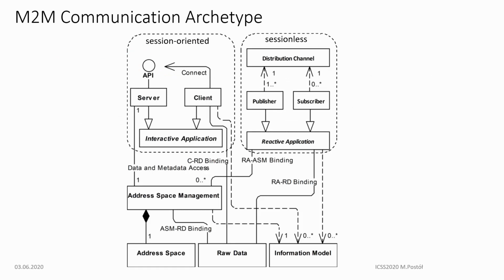In general, the semantic context may be agreed against at runtime or design time, but always in advance. According to the proposed model, this process is supported by the address space management and information model concepts, which may be partially implemented in compliance with the OPC UA standard. The runtime approach is straightforward after establishing the session, because the session is a tight relationship that can be used to exchange appropriate metadata. In the context of the metadata exposed by the mentioned entities, the client can select what data it is interested in.